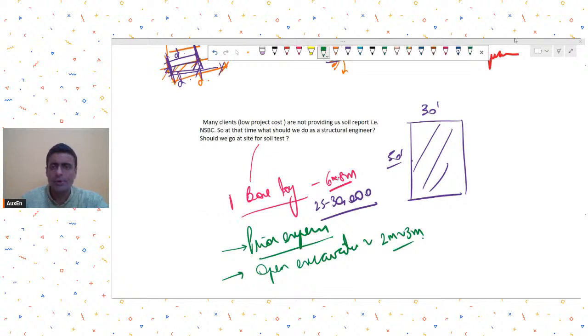That is a problem that engineers may face, mostly in the northern plains of India, from let's say Punjab to Bengal, even in Bangladesh, even in Pakistan, in the alluvial belt, poor soils are an issue. So there they have to be more careful. They have to go for piles, or they have to take a very low SBC. But yeah, these are the options you have.